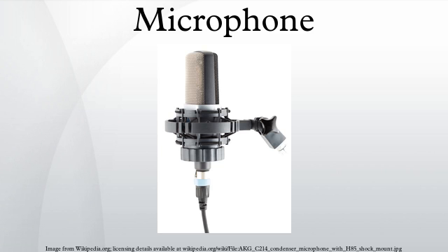They add very little to the original sound. Being pressure sensitive, they can also have a very flat low-frequency response down to 20 Hz or below. Pressure-sensitive microphones also respond much less to wind noise and plosives than directional microphones. An example of a non-directional microphone is the round black 8-ball.